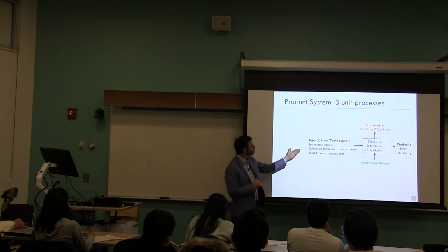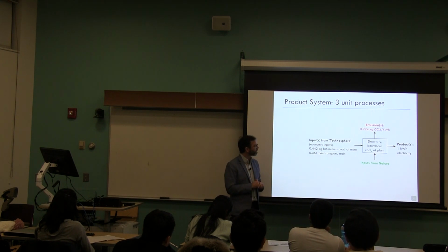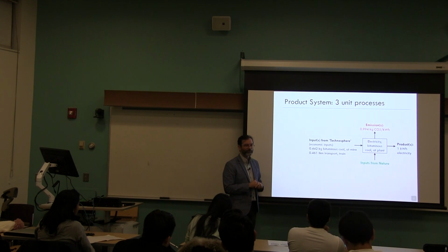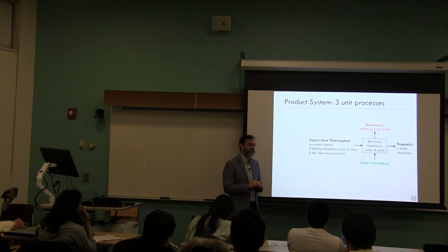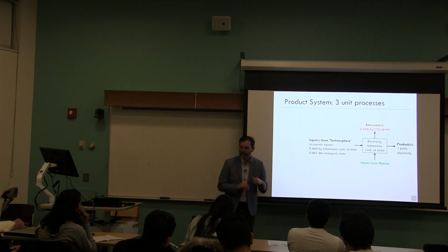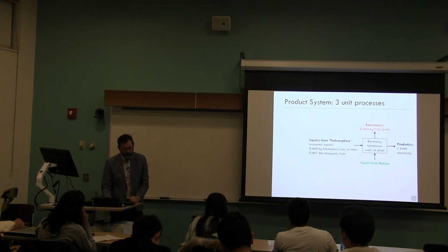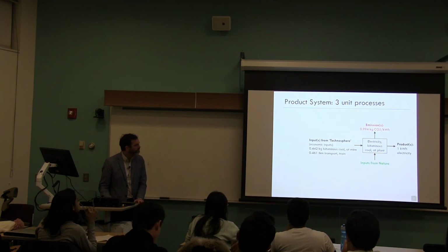Right? So let's say in this example, you need 0.442 kilograms of bituminous coal with a certain heat content in order to generate 1 kilowatt hour of electricity in this power plant. And then based on how far away you are between the coal mine and the power plant, you can estimate the ton kilometers, which is the product of the tons of freight times the distance in kilometers, to get that melded unit, ton kilometers, in this example, 0.461. So we have those measurements now.